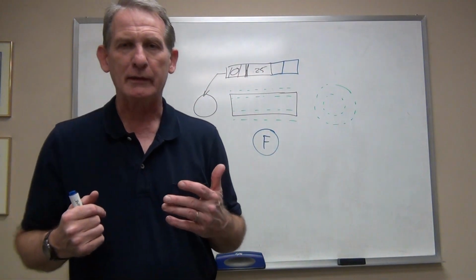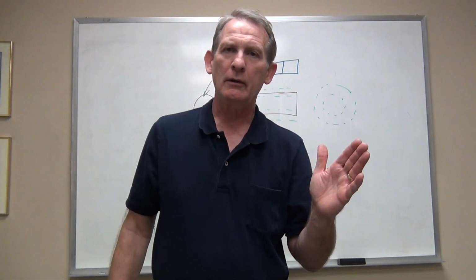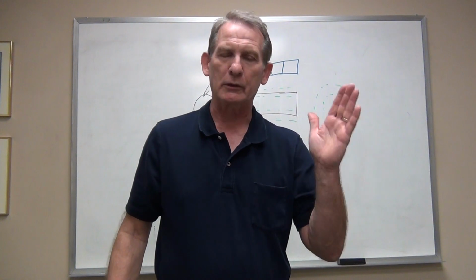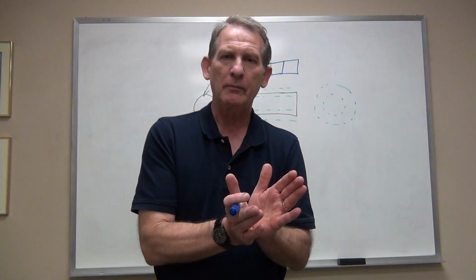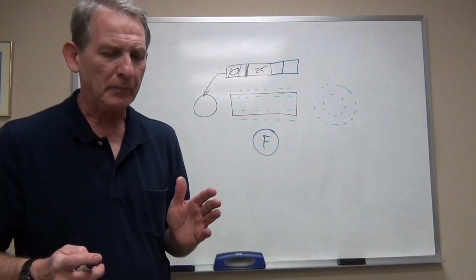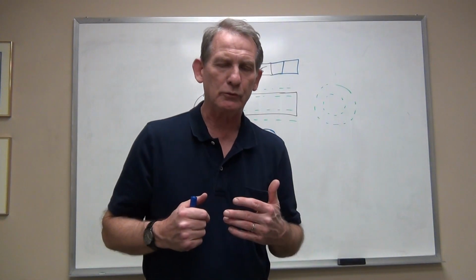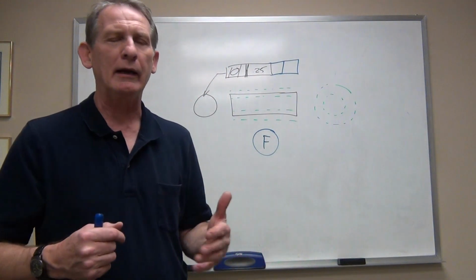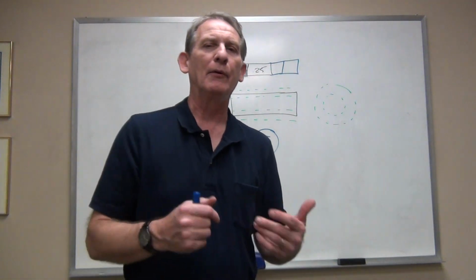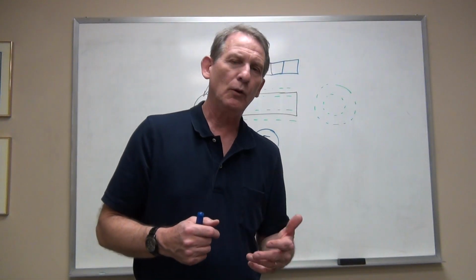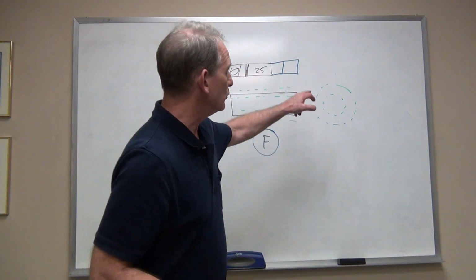In tolerances of orientation, we are always going to compare the state of one feature that we're concerned about with another one. That is essential to orientation. We have to be oriented relative to something, and we have to tell the inspector what we are orienting to, and that's what goes in this box.